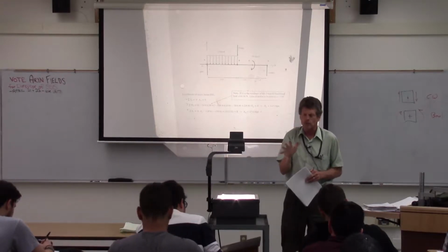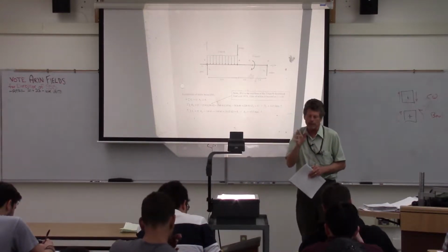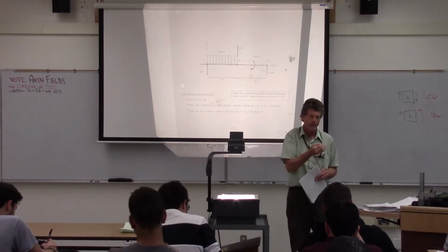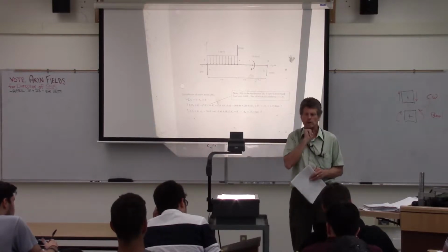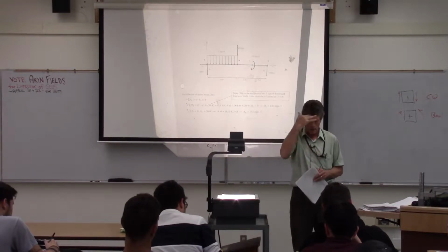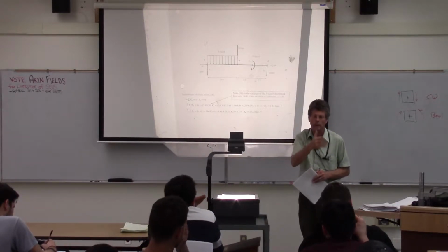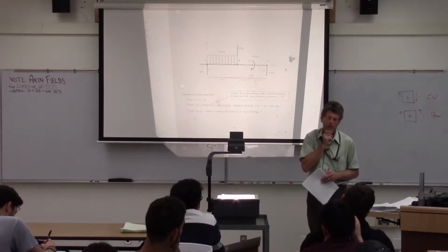Now, the funny thing is when we have a positive moment, and we have a positive moment diagram, it depends on whether you're designing reinforced concrete or steel, because they'll show it on the opposite side. Concrete likes to show positive moment on the bottom because that's where you put the steel. So it's a visual aid to the designer to say, oh, I've got positive moment there, I need to put steel in the bottom of it.